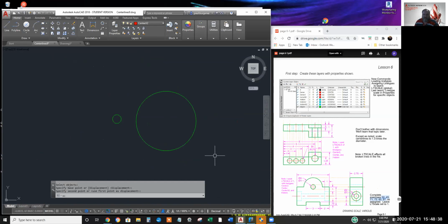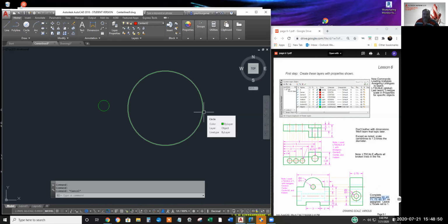Now, what happens if your drawing happens to be twice as big? Well, now the bigger one is outside of the range of the center X2 line type. There's no way of using a simple red line that you'll have a single plus sign in the middle. It'll turn into long, short, long, short, long.